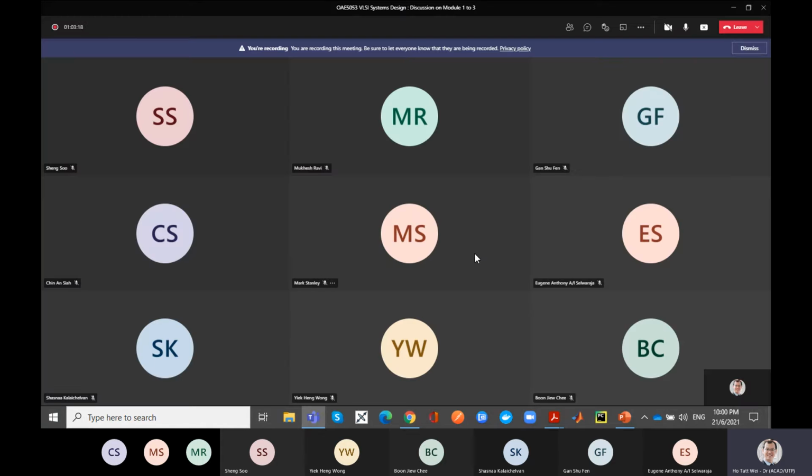And yeah, I know BJ just recently asked because it took him like 24 hours to finish. If you get to the point where you have the spec file, the pre-place and route and post-place and route static timing analysis, and the synthesized Verilog file using the standard cells of the library, this is good enough. You can begin your analysis already. In fact, I don't need all of you to run it on your laptops. If you want to work in a group, just make sure that somebody has gotten to this part, synthesize. You can just reuse that file. It's okay. It's more that you understand the process.